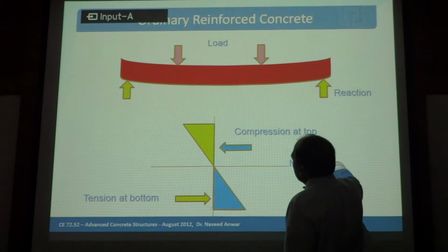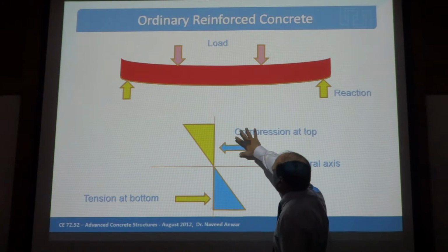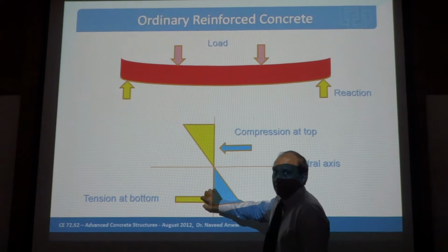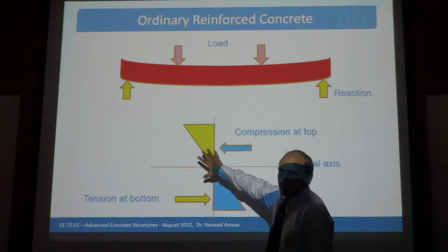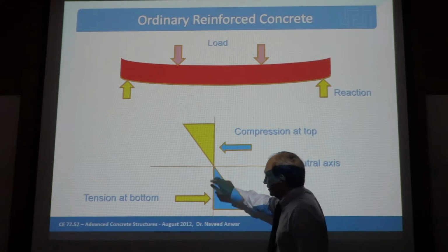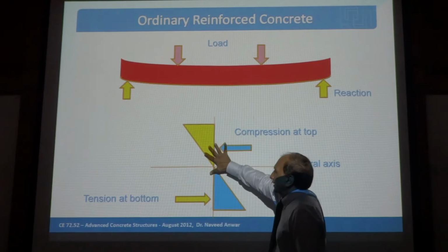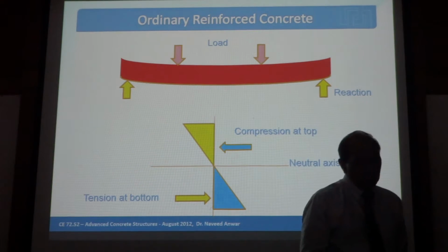So, but you still can sum up the tension and the compression at the bottom. If you can replace the entire tension by steel, this can still work, right? So all of the tension, calculate and replace it by steel, and this one by concrete, you can provide the capacity through this couple.